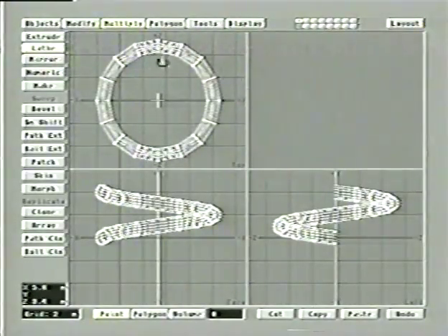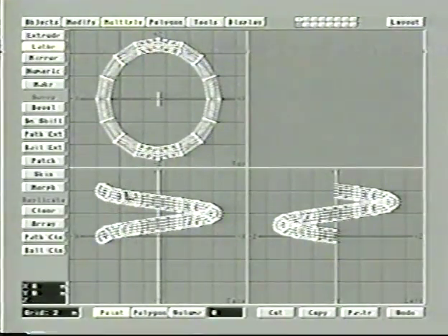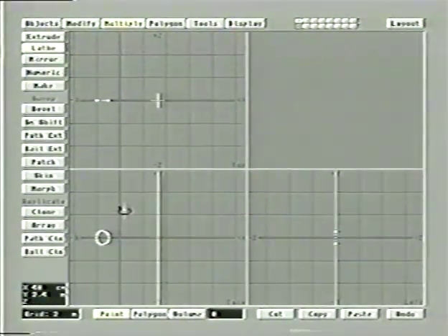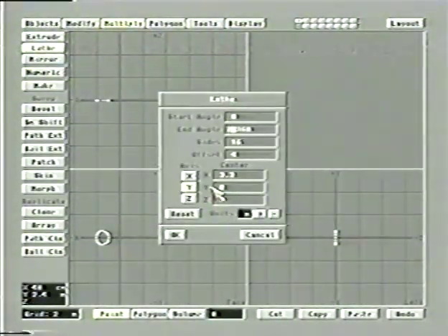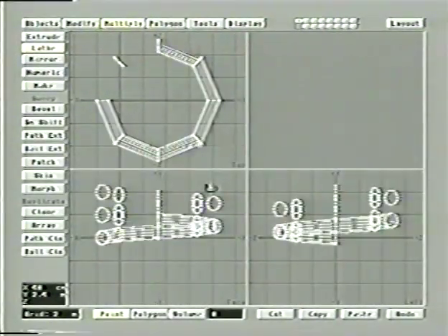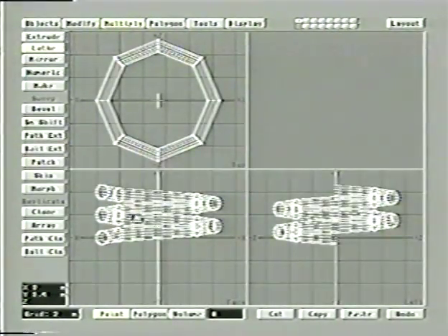Now, this is where it can be handy to add more degrees for our end angle. If we set it to 720 degrees now, it's going to sweep it around this way twice as it raises it up. So let's undo that. Numerically change end angle to 720. And so now it's spinning it around a couple times. The problem is, from the top view, it's very squared off.